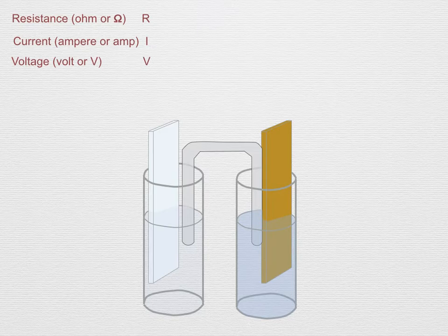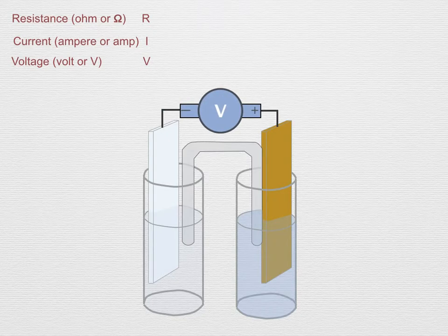A voltmeter is what is known as a high impedance device. It means that its internal resistance is very large, especially compared to other components in the circuit. As such, it draws extremely little current itself and provides an accurate voltage reading. When we measure the voltage of an electrochemical cell, we draw a vanishingly small current from it and obtain an accurate voltage reading. The cell does not change much because the current drawn is so small.